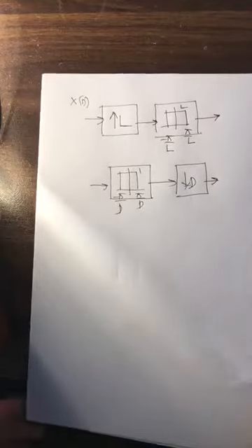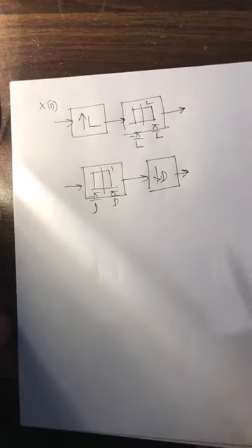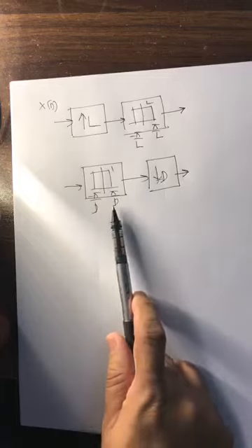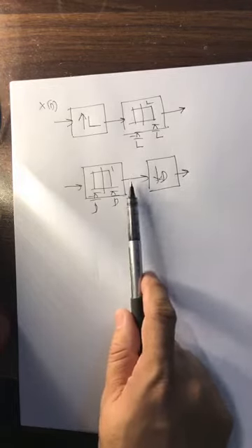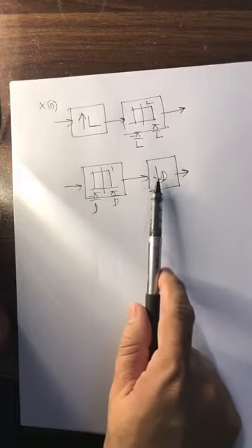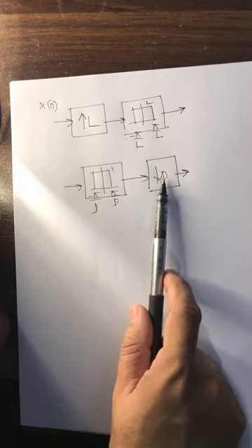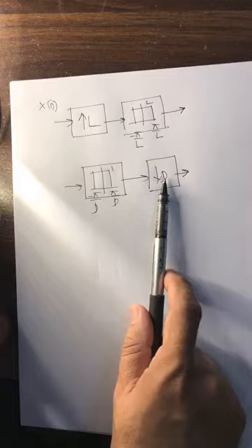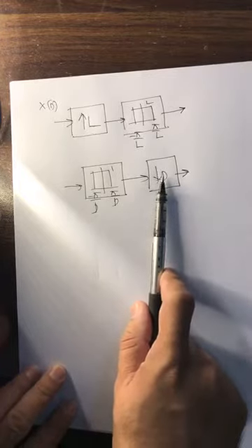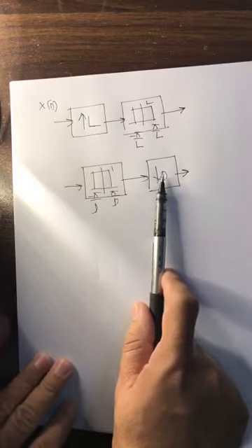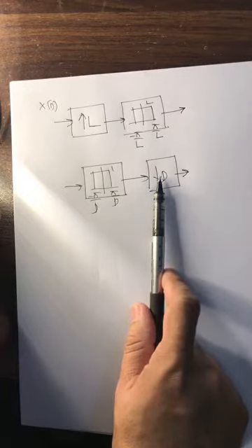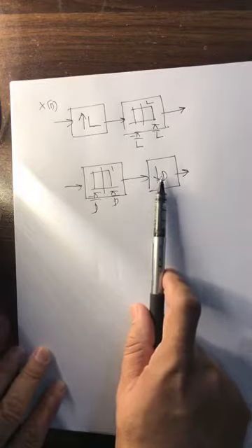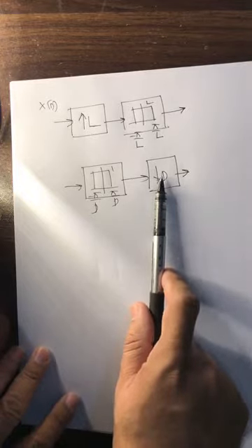So now we have seen that decimation is primarily you pass it through a pi over d filter, so that you clean up the spectrum before you expand it, means that you're throwing away samples. In case of voice, we have just seen the quality of voice going down, but why do you do this? Because you can reduce the cost of the system to half. If you do decimation, you can reduce the cost of the system to half.